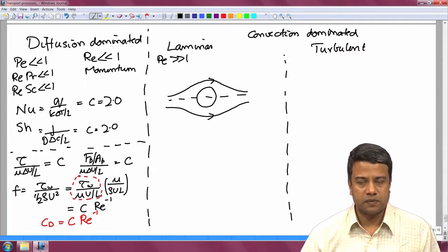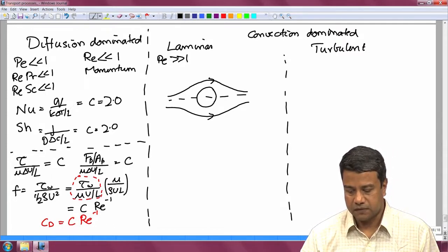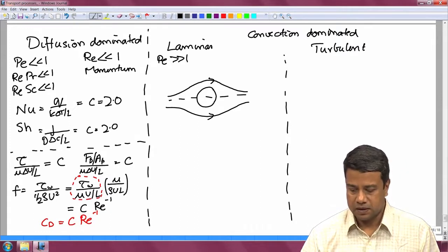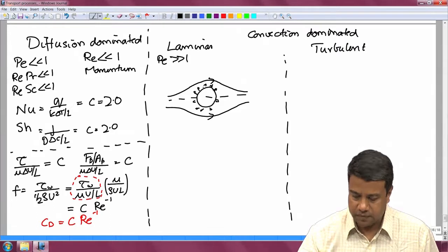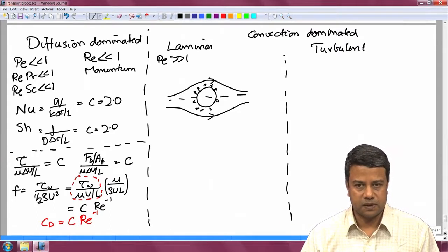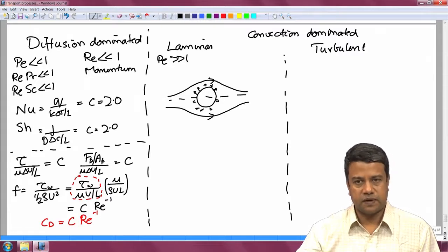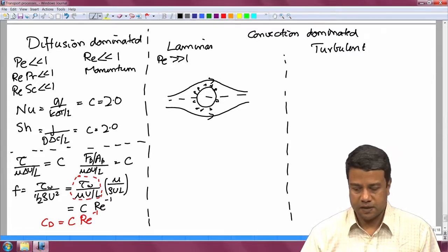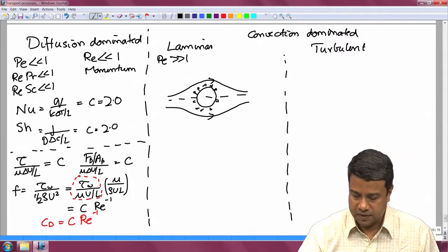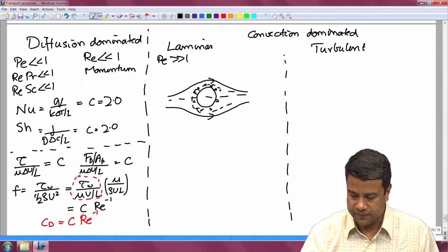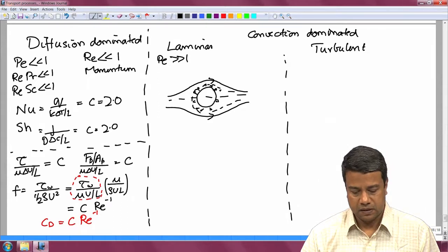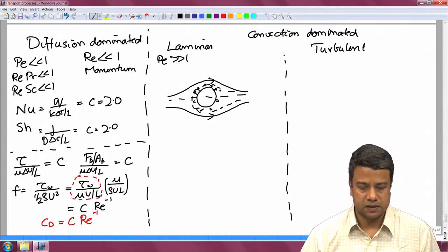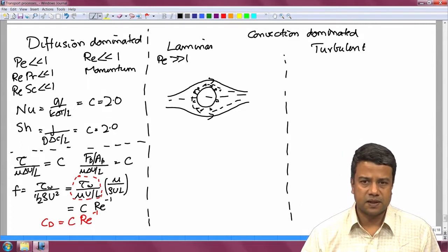And when diffusion becomes important, if you are in the limit of high Peclet number, then the material that diffuses out will not diffuse very far before it is swept backwards by the flow, because the Peclet numbers are large. Therefore, this diffusion will be restricted to thin regions near the surface, whether it is mass or heat, when the Peclet numbers are large. This is something that we will analyze later.